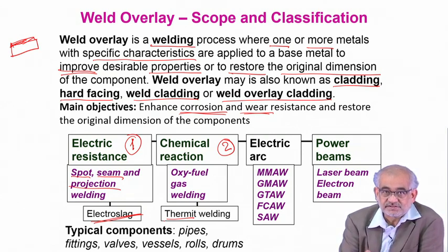You use a mixture of aluminum and iron oxide, and then you heat using the oxy-acetylene oxy-fuel torch, and aluminum reacts with iron oxide, substitutes Fe from Fe2O3, and in turn creates alumina, which is a slag phase. But molten iron seeps inside the crack or the gap and welds the two pieces of iron, the rail, and that's how you can join. So that's a typical thermit process.